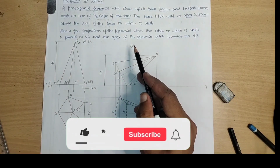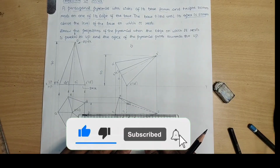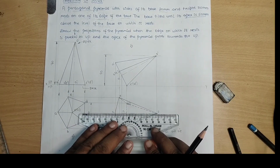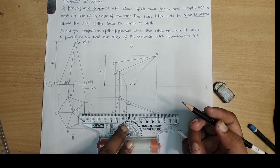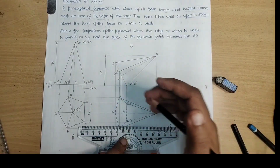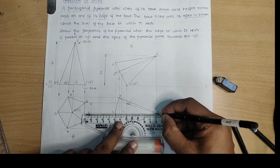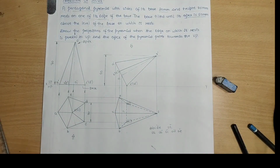Observer is looking from the top. Observer is very close to the point O and A. Henceforth, this becomes a visible line. That is a straight, thick, continuous line. But already a part of the line, O to O1, is the axis line. So what happens? Remove the axis line. Upon that, let us go for the straight, continuous line. So this is how you are supposed to break down.